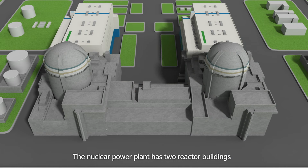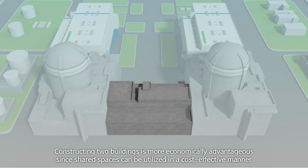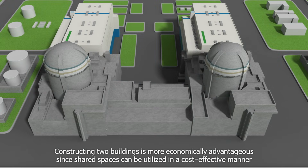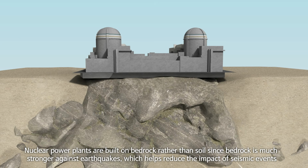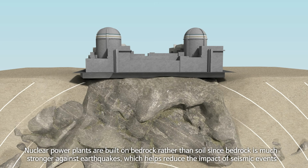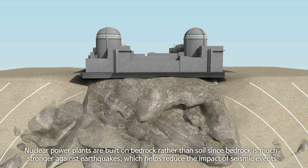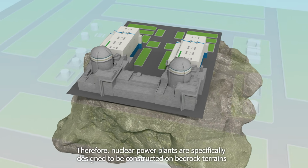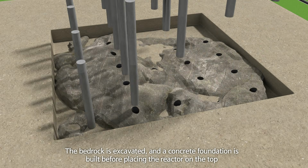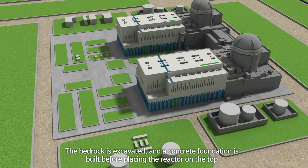The nuclear power plant has 2 reactor buildings. Constructing 2 buildings is more economically advantageous since shared spaces can be utilized in a cost-effective manner. Nuclear power plants are built on bedrock rather than soil, since bedrock is much stronger against earthquakes, which helps reduce the impact of seismic events. Nuclear power plants are specifically designed to be constructed on bedrock terrains. The bedrock is excavated and a concrete foundation is built before placing the reactor on top.